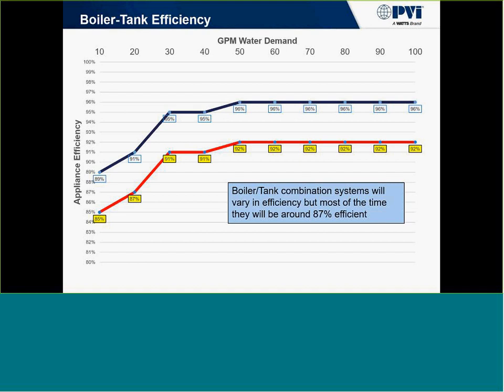And if you add all the other components into that system, it actually derates their efficiencies by usually an average of about 4%. So that's something that we definitely need to take into consideration when we're designing or talking to owners, to be able to communicate exactly what those efficiencies mean and how it's going to be applicable for their building.